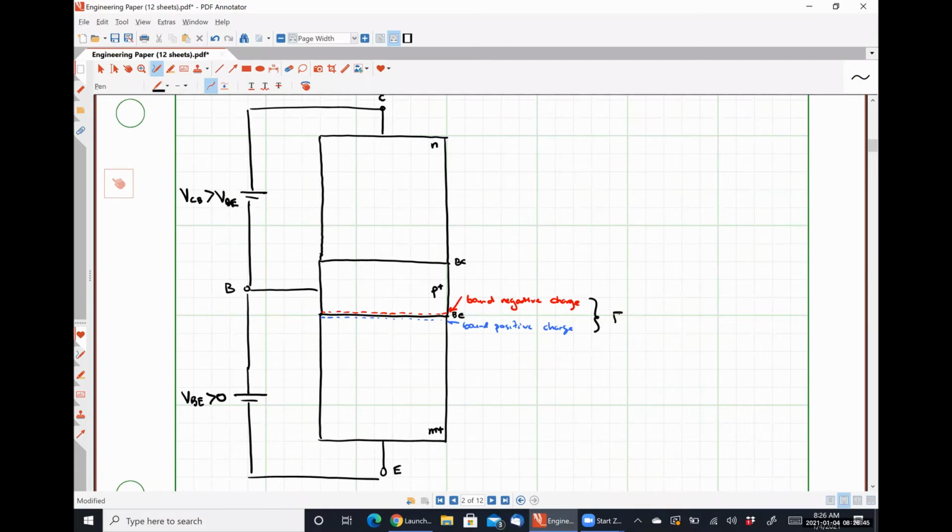And the electric field of the base emitter junction, actually I'm going to call it EB. The reason is because it's directed from the emitter to the base, because the positive charge is on the emitter side, is going to be reduced by the forward bias voltage. So we're going to see that we have a relatively small electric field oriented in the up direction in this drawing. Okay.